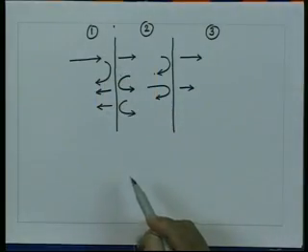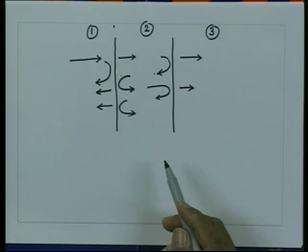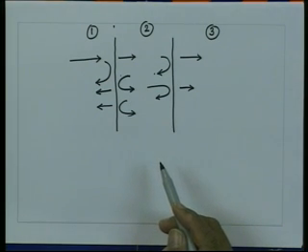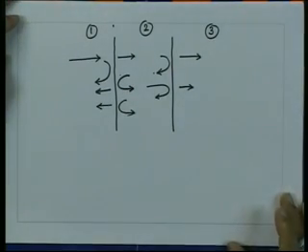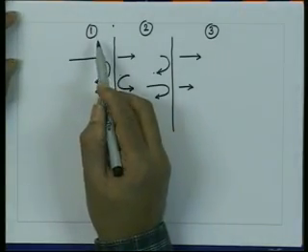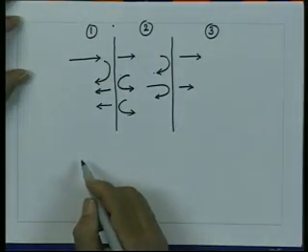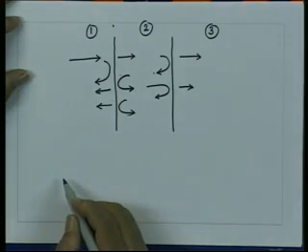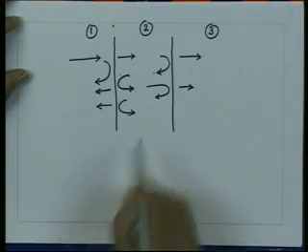So, now we can write down the reflection coefficient for each of these boundaries and the transmission coefficient on each of the boundaries, and then find the total summation, and from there we can get the total reflection and the total transmission. Now, if I say that the reflection at the ij boundary, that means for the 1 2 boundary, would be gamma 1 2.